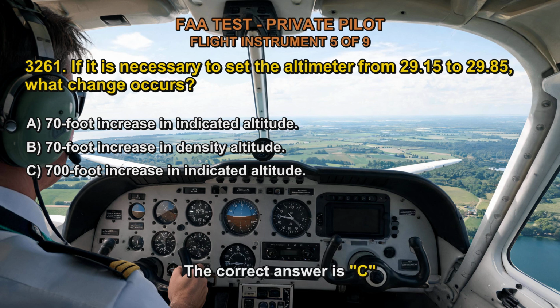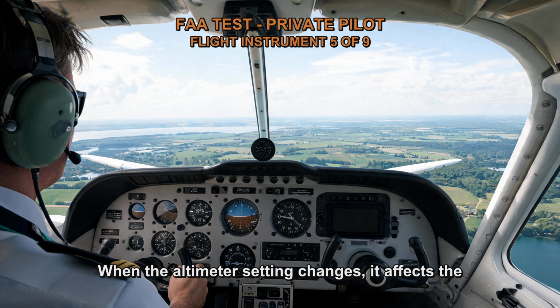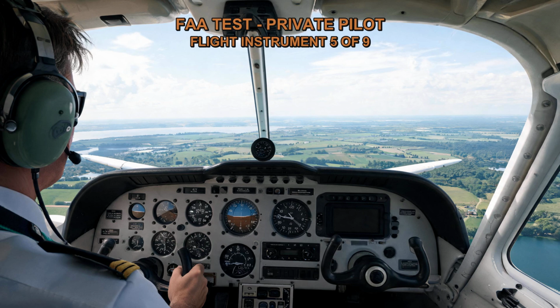The correct answer is C. The altimeter setting represents the barometric pressure at a given location. When the altimeter setting changes, it affects the altimeter's indication of altitude. Each inch of mercury change in the altimeter setting corresponds to approximately 1,000 feet of altitude change. In this case, the altimeter setting is being changed from 29.15 in Hg to 29.85 in Hg, resulting in a difference of 0.7 in Hg.